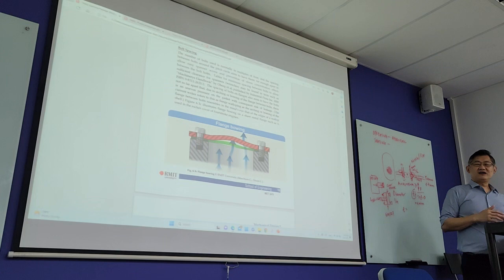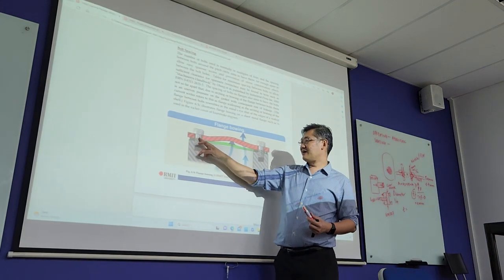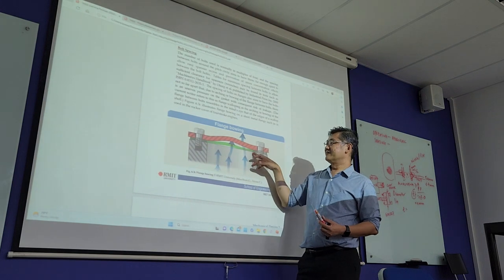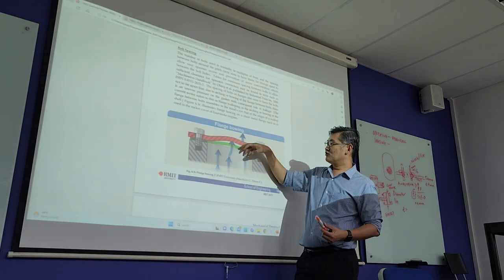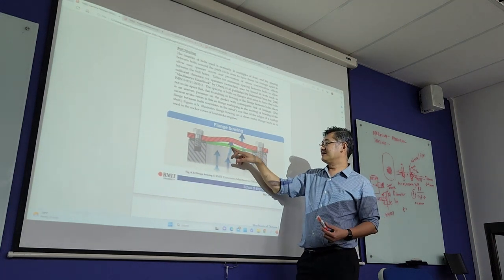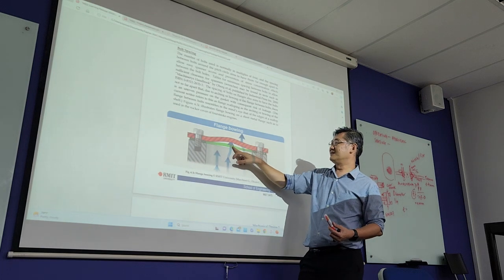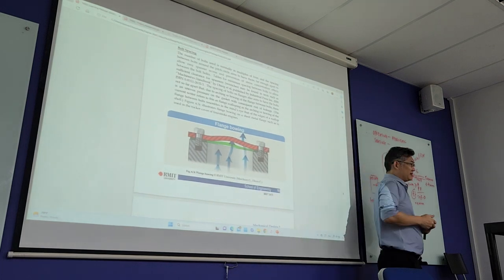And some of these are the defects. If, let's say, you tighten too much, over-tighten, of course, you can see you actually cause this plate to deform. Means what? Means now the gasket cannot contain the pressure, so you have a leak. We call this flange bowing.